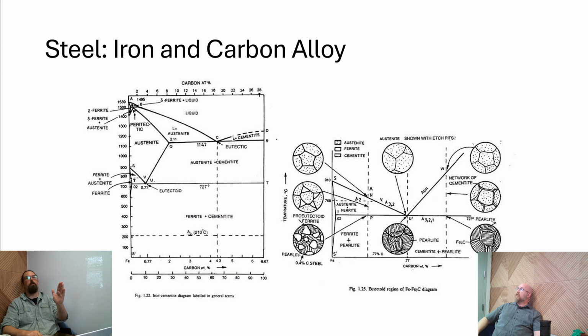We got a little bit off topic here when we were giving some examples about why we care about these different states of matter. Happy we're talking about explosions. But let's go back and define what we meant by eutectic one more time to bring everything back. It's that minimum point, basically the lowest melt temperature, so it's going to gravitate towards achieving that mixture because it can achieve mixture when it's liquid. And so that feedback cycle that you get for the eutectic point is what is happening there.